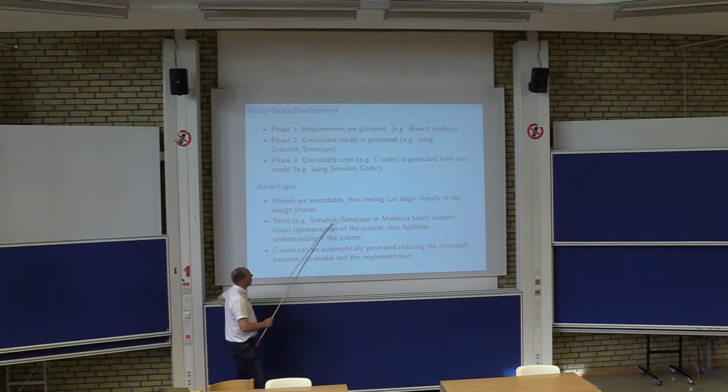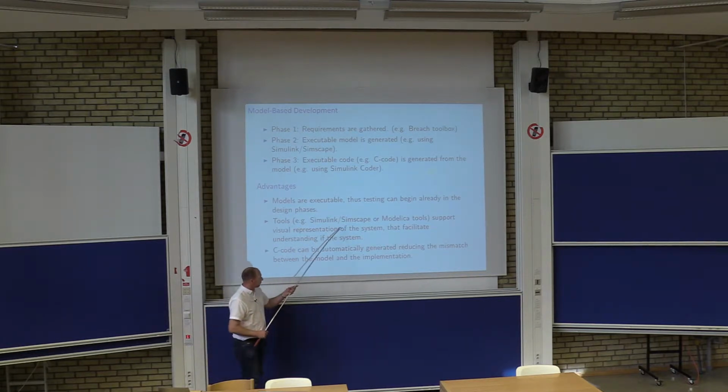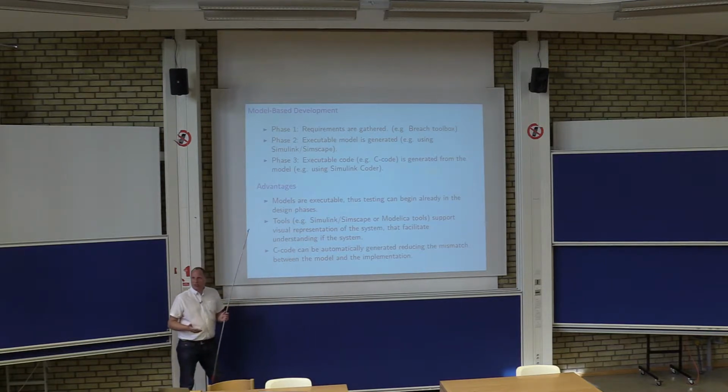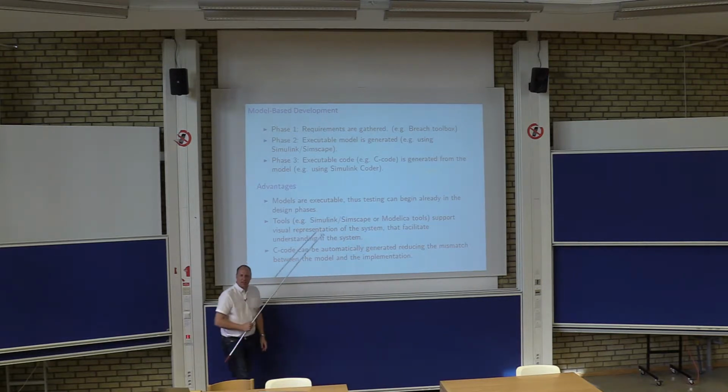While Simulink has traditionally been the language to describe physical systems, there is a strong trend to move to equation-based modeling languages of the physical systems instead. Modelica is the international standard that is supported by different tools, and Simscape is the dialect of Modelica in the MathWorks toolchain.